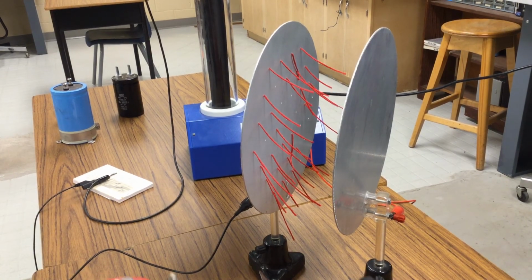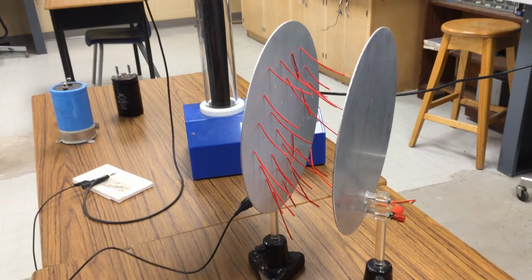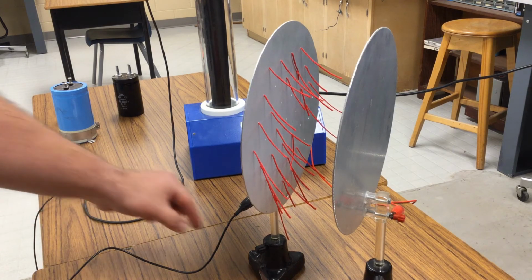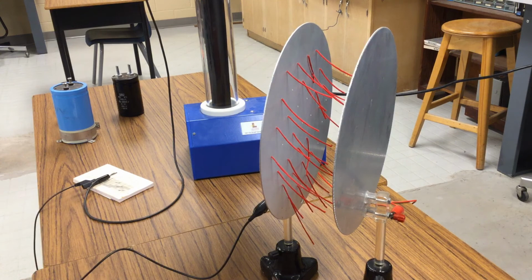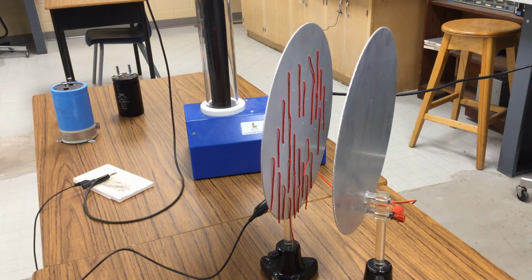Because this much capacitance can hold a lethal amount of charge. And that's the problem with capacitors: they're sitting there, they can hold their charge for a long time, and that can be potentially fatal if it's a high enough voltage. To discharge a capacitor, all you have to do is give the electrons a place to discharge through.